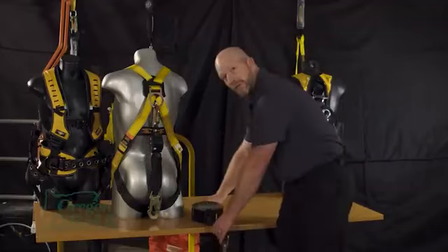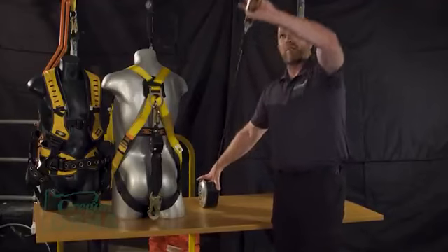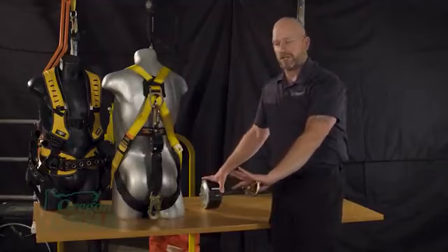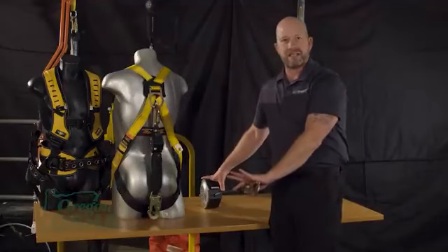now we get to a condition where if this is my walking surface, this is attached to an anchor, and now my D-ring is up in the air 5 foot occasionally based off of the worker's height, and then they fall. Because this works like a seat belt, what happens is we're creating acceleration on a device that's not designed to take that.